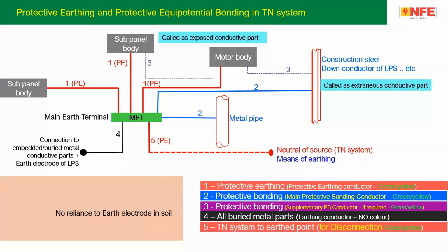So, fundamentally, a lot of change happened after 2020, especially in the CEA regulation as well as in the upcoming documents such as the NEC. Now, earthing in a building means you interconnect all the metal parts, the simultaneously accessible conductive parts in your building. As a result, there is no shock. It's a very simple idea. Potential does not create shock. Potential difference creates a shock. So you bond all the conductive parts in your building. As a result, there is no shock.